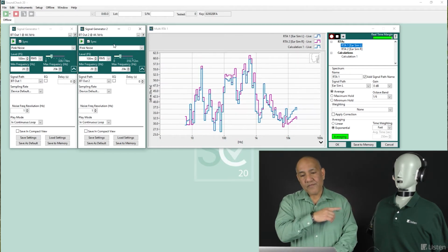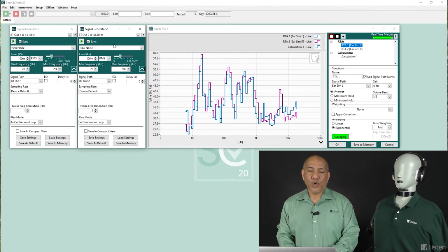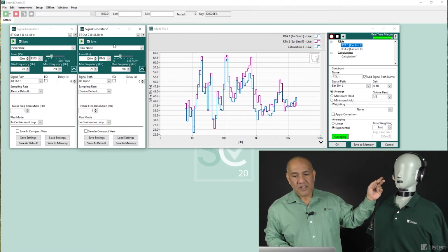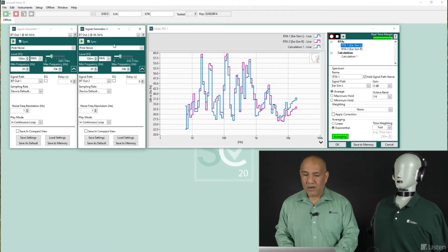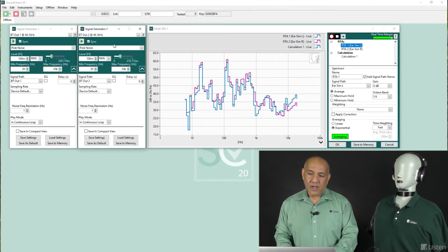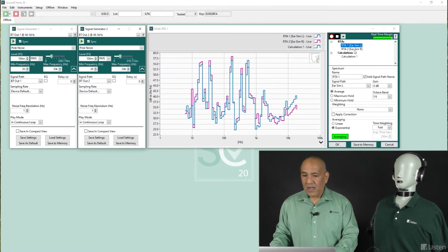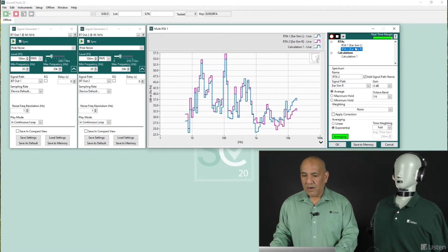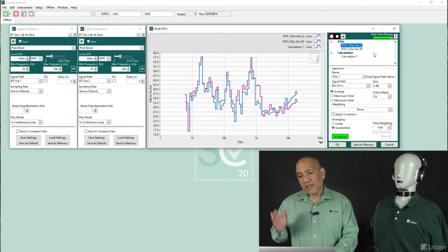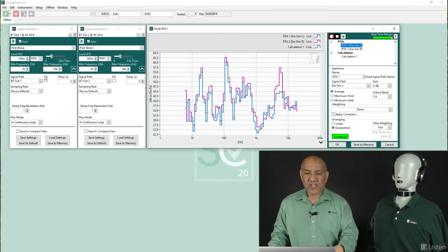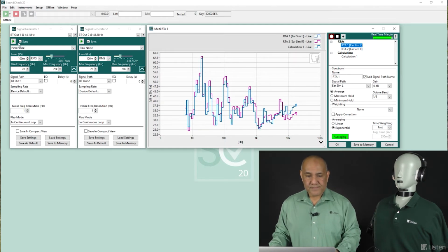Once I play to the headphones, what you see on the right side is I'm going to capture the RTA spectrum of the ear simulator inside of the mannequin through the left and right ear. And that's what we're looking at right now. Here are the settings for the left ear. Here are the settings for the right ear. Okay, so this is a 6th octave resolution. Let me just hit play and you'll see the spectrum in my display.